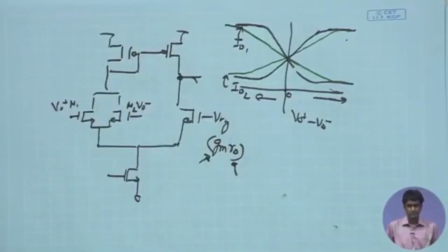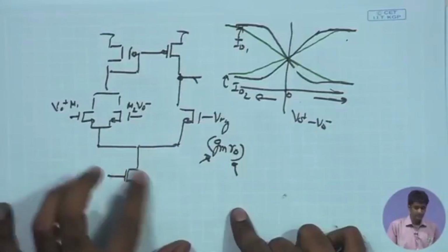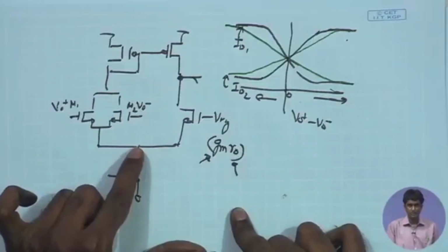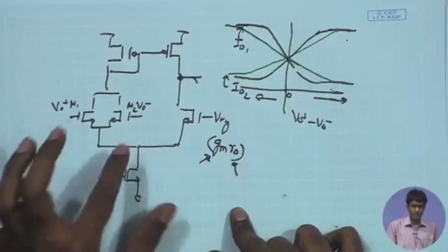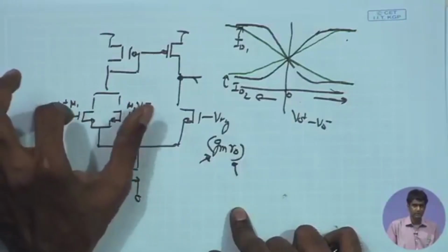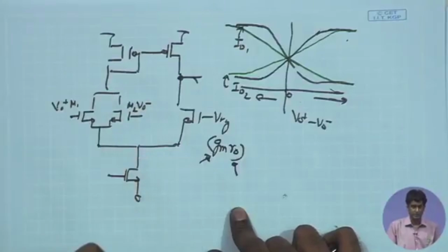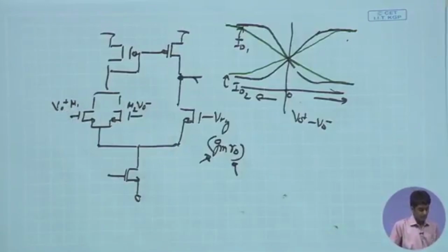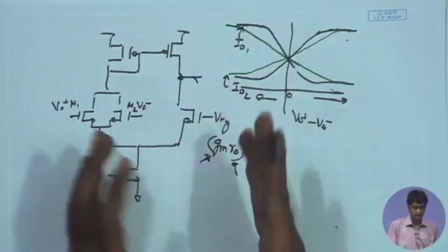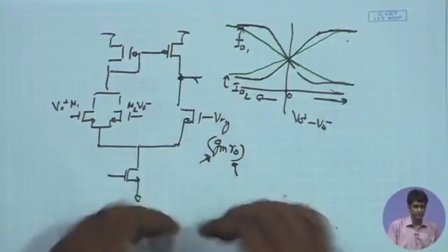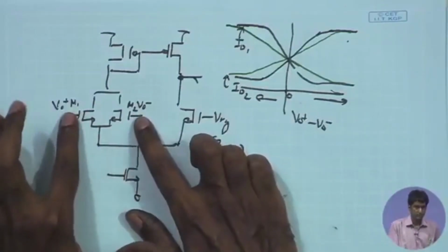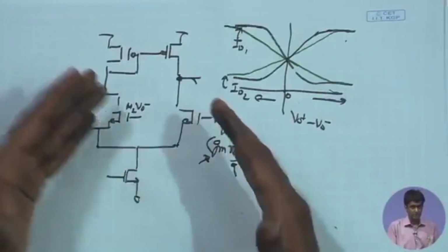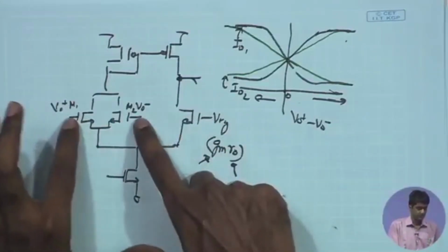So that is another important feature that we should consider while looking at the sizing of the common mode device. And another point will be to size this tail current source. If you make the tail current source sufficiently large, it will be able to handle a lower input signal over here, and that also increases the maximum differential swing that the common mode device can handle. That is another way, and we can have other alternatives also in cases where the output signal swing is sufficiently large and extraction of common mode using this scheme is failing. We can go for other schemes where you can handle a larger output signal and where it is not constrained by such a differential swing.